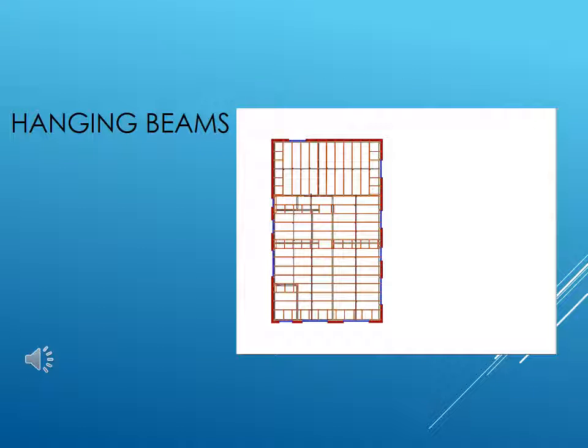Hanging beams. Hanging beams support only ceiling loads, and so their function is to pick up the ceiling joists, and where their span is too long, then what we actually need is to fit a hanging beam. My solution for maintaining the coupling of the wall frame over the bedroom where the ceiling joists run in the opposite direction is to run a full length hanger from one side of the wall frame to the other.